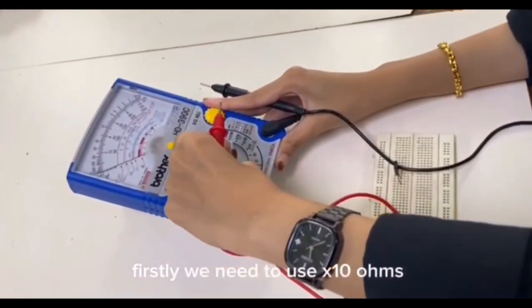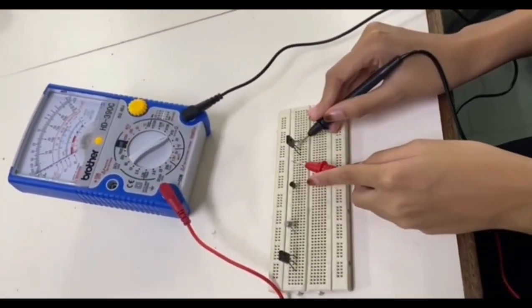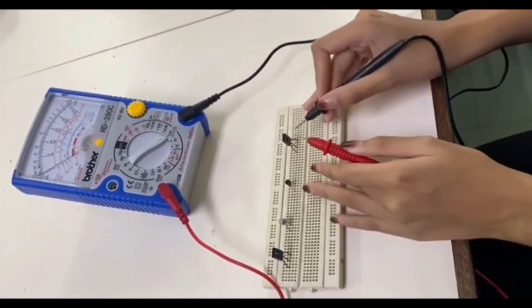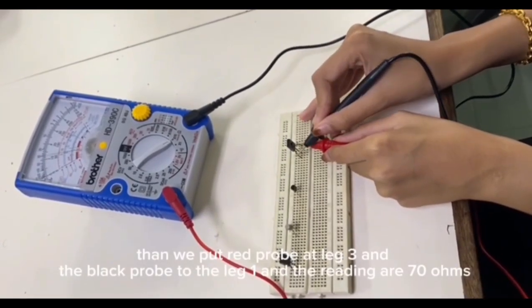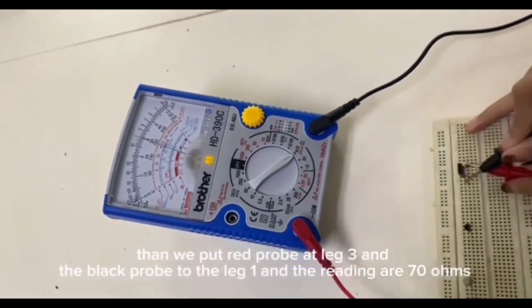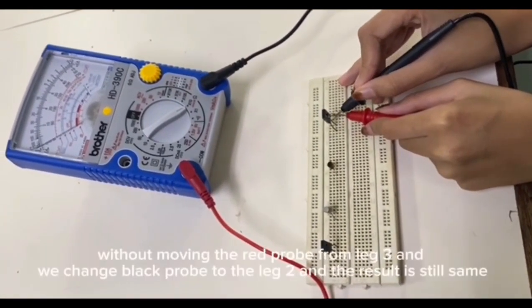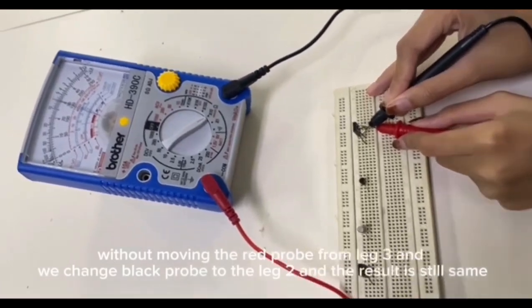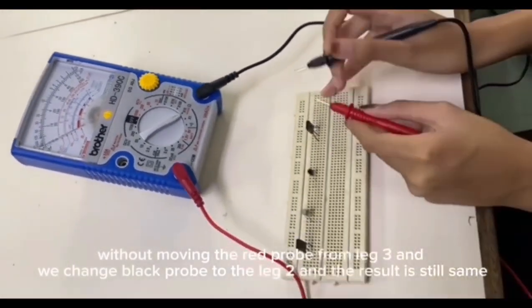Firstly, we need to use the times 10 ohm range. Then we put the red probe at leg 3 and the black probe at leg 1. Then we got a reading of 70 ohms. Without moving the red probe from leg 3, we change the black probe to leg 2 and the result is still the same.